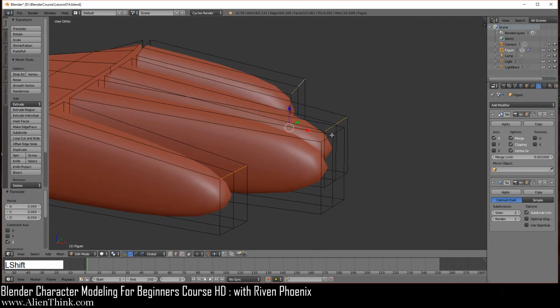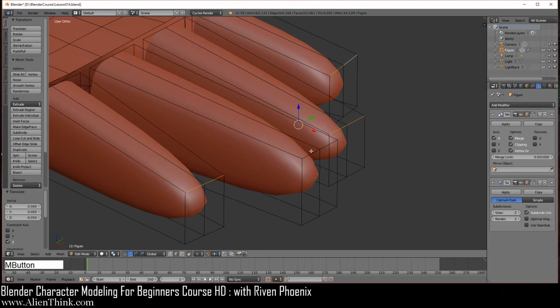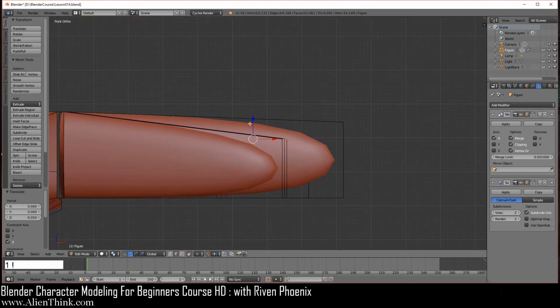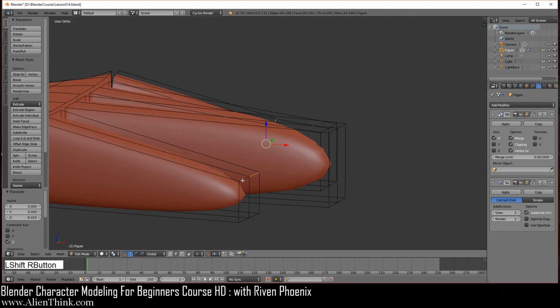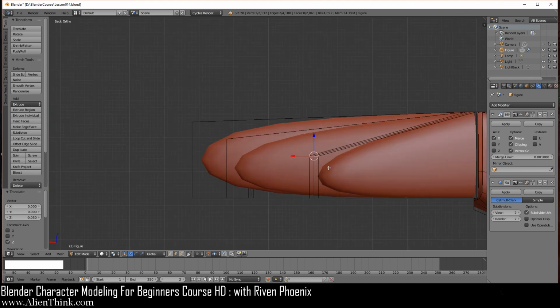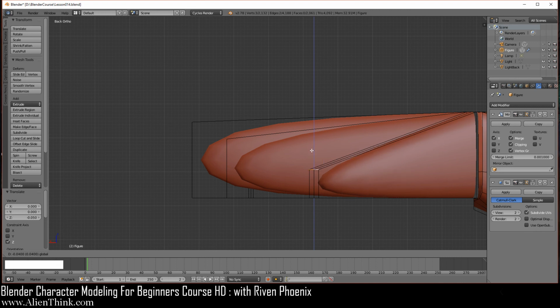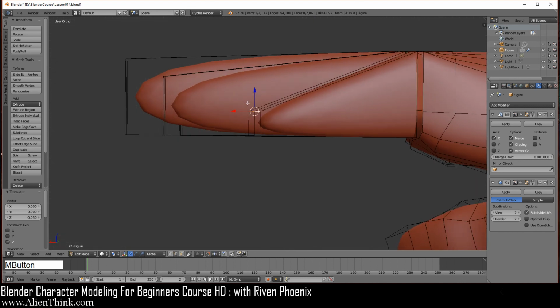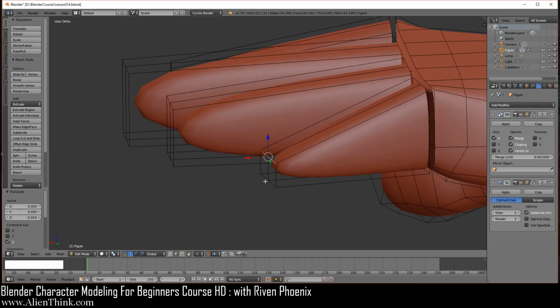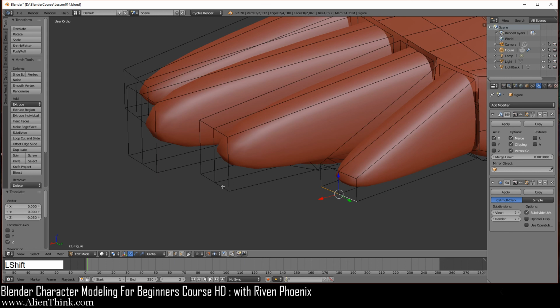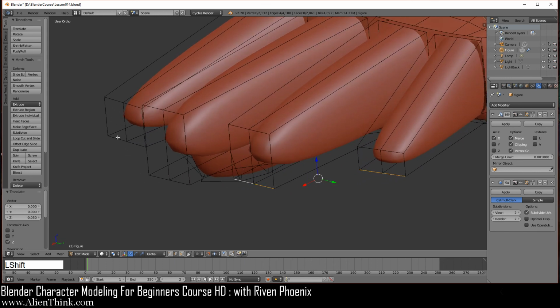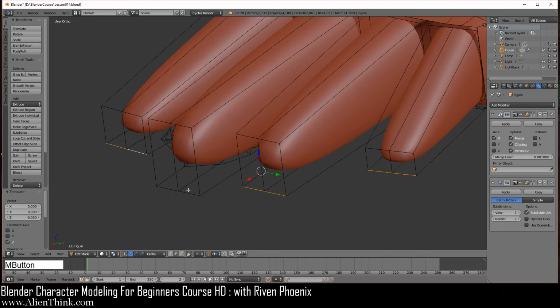Now rotate over here. Go ahead and just rotate it again. Deselect these 2. Go back to your front view. Bring it down 1, 2, 3, 4, and then 5. Middle mouse button to rotate. Deselect this one. Now do Control 1 to get on this side and just bring it down 1, 2, 3, 4, and then 5. Okay. Now just rotate over here. What you want is really just this edge over here, and we want this edge over here, and we want this edge over here. Okay, we're not going to select this edge.